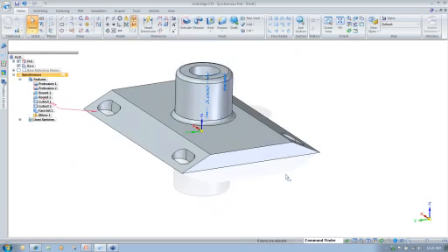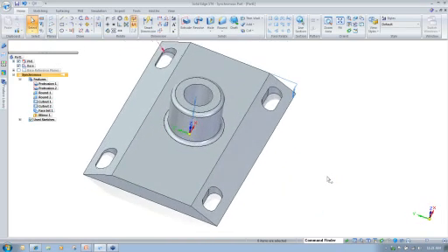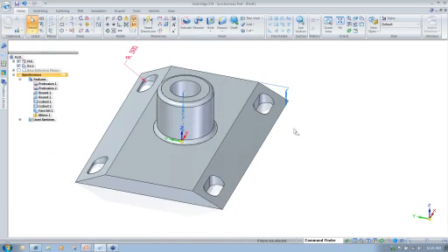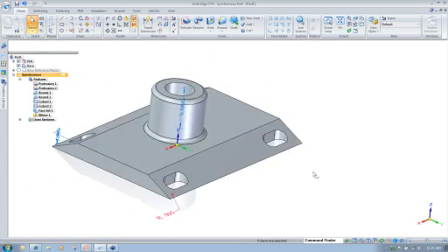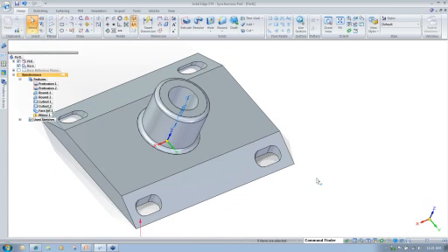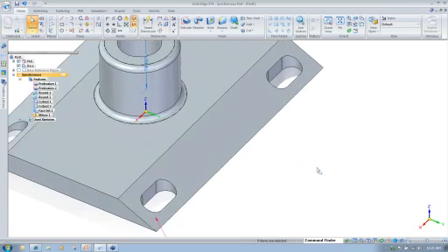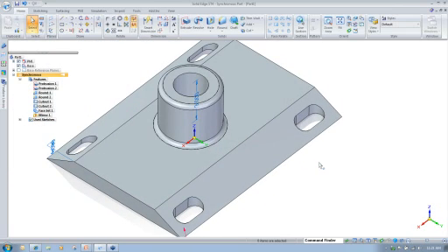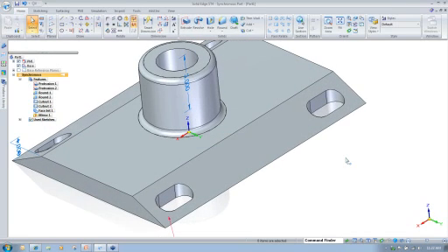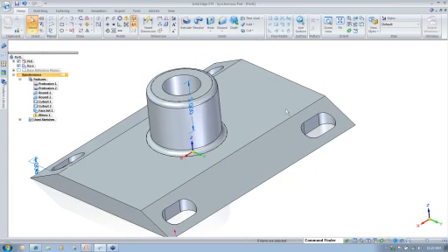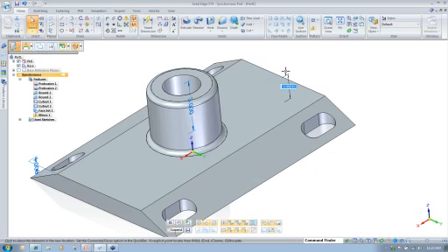So now you can see that our mounting plate's taken shape, and we have some angles in there. We got all of our 4 slots in there quick and easy. We've copied using the steering wheel. We've moved using the steering wheel. We've done some sketching in the synchronous environment, and it really took some time to have this mounting plate take shape in the synchronous environment. The next thing I want to show you is, again, we can always just pull